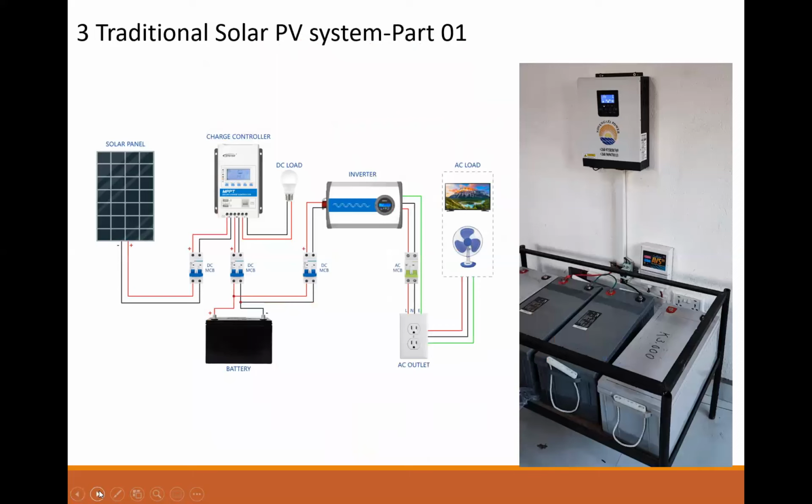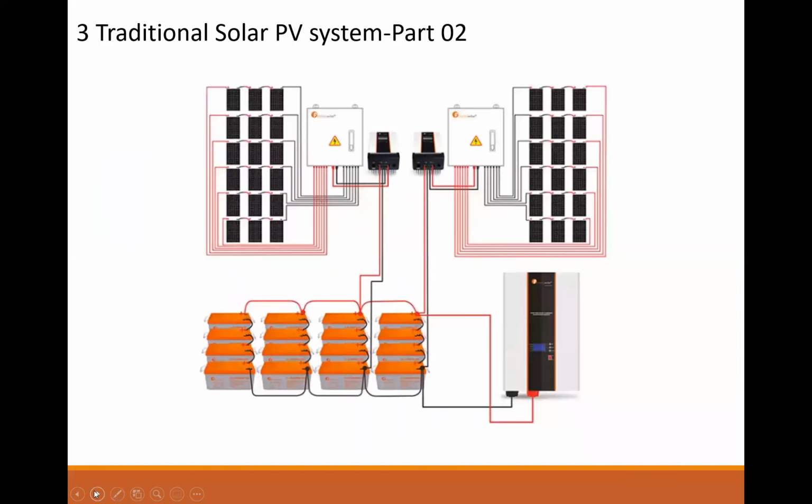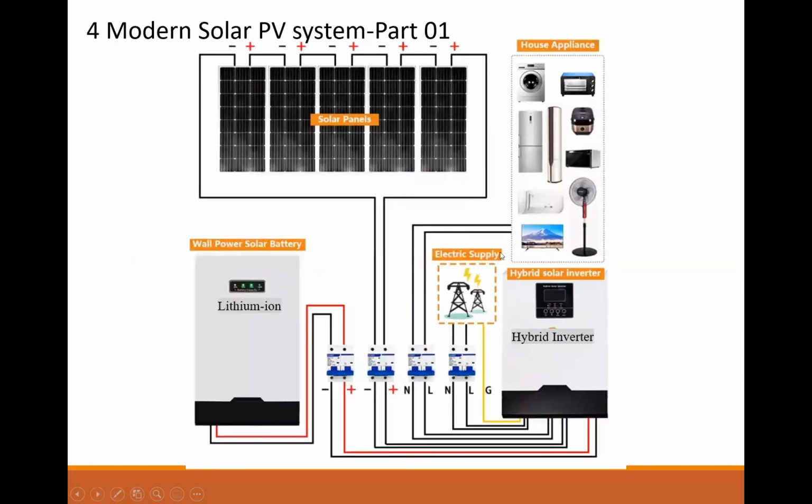For complete off-grid, where you don't have a diesel generator and you only need power from solar, it becomes easier to make a decision to go with one which has got no inbuilt charge controller. But if you are going to have a standby utility or even a diesel generator, you can go for the one which is hybrid and also with inbuilt charge controller. So these are some of the things that we continue to discuss and look at.